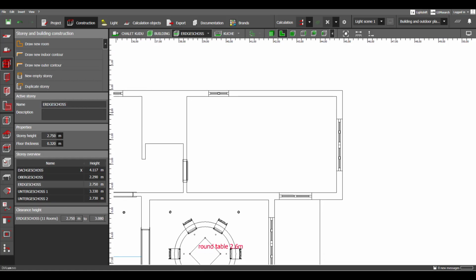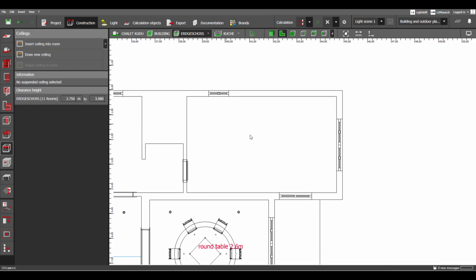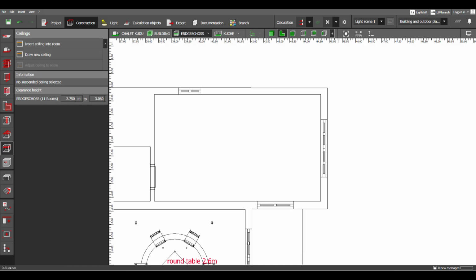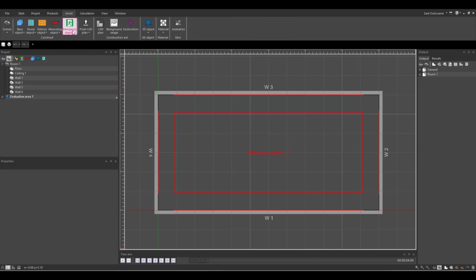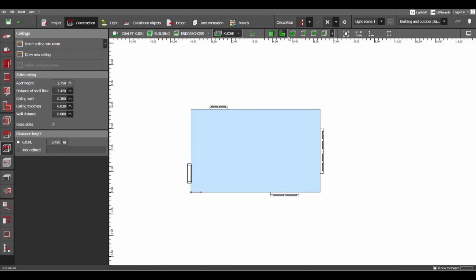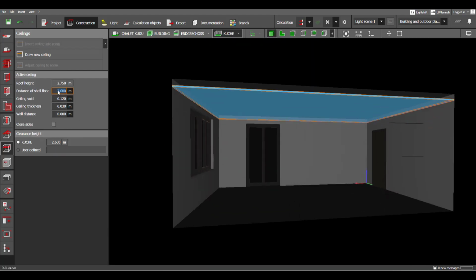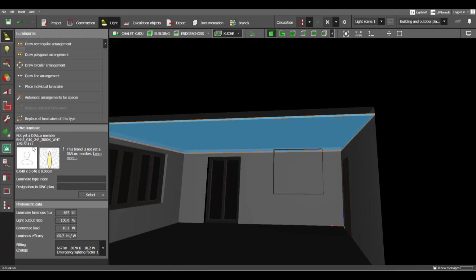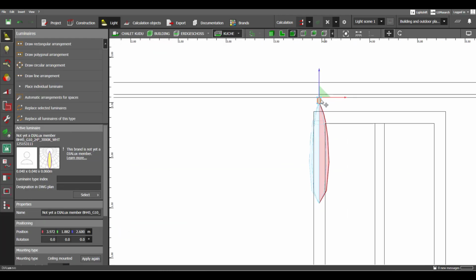Ceilings or false ceilings are a very important modeling element. Dialux Evo has that, but Relux doesn't. When placed, a false ceiling by default becomes the ceiling. If you place any light, it goes directly to that false ceiling. You can also do a lot of great things with it. Dialux did an amazing job with that.